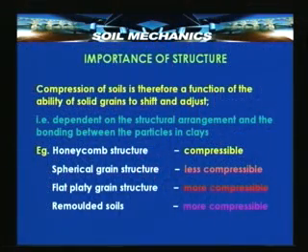The structure which is of this nature, which is compact, may not be very critical from the point of view of consolidation, because much readjustment of particles is not possible. Whereas, there are other types of structures like the honeycomb structure or the flat platy grain structure, or even simply remolded clay which has lost part of its strength, where the compressibility could be more and more, could be of a higher order, and it is for those really where the compressibility is of a higher order that we really need to look into the phenomenon of consolidation in detail and depth.